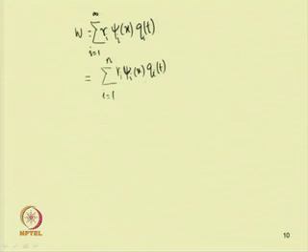These psi terms can be obtained. The psi terms can be an admissible function, or it can be the eigenfunction of the system. When one considers the eigenfunction, then the resulting equation can be reduced to a simpler form, but if one considers an admissible function which is not the eigenfunction, then modal interactions will be there in the equation of motion.